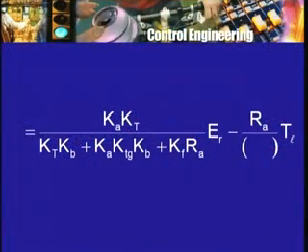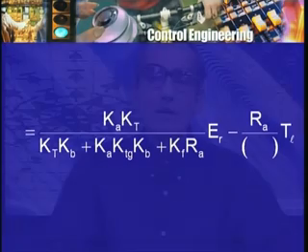But you can compare this with the expression that we had earlier, when there was no such arrangement of feedback, and you can see that the load torque change with the feedback, the speed change rather, because of load torque change with feedback, will be less than the speed change caused by load torque change without feedback. So increasing Ka, in fact, will reduce the effect of load torque changes, or will reduce the effect of disturbance on the drive.